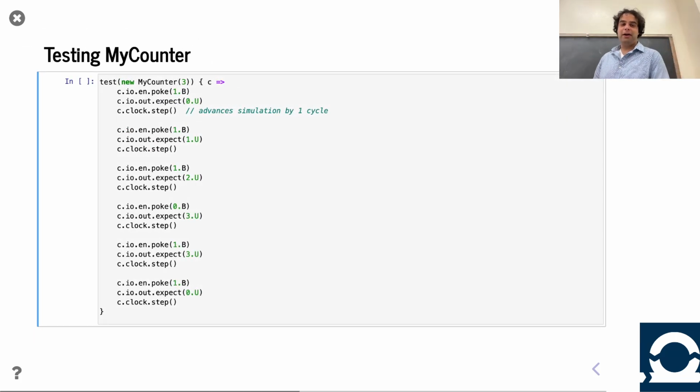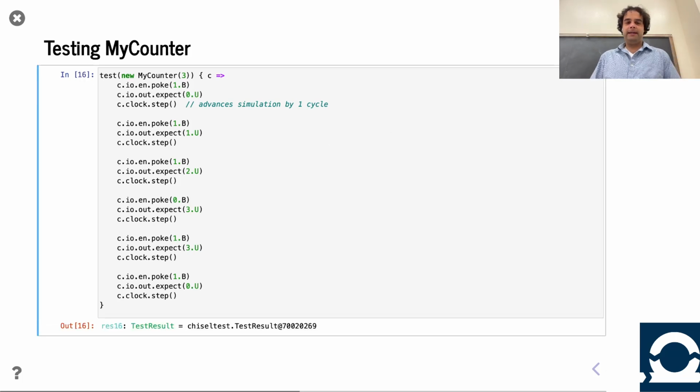So here's that test we're talking about. Yes, this test has this nice concise name because I have that imported earlier. So this is a test of the counter. And this is an exhaustive test, but what do we do? Well, we say I want a counter with maximum value 3, turn on the enable, and say initially coming out of reset, yeah, it better be 0.